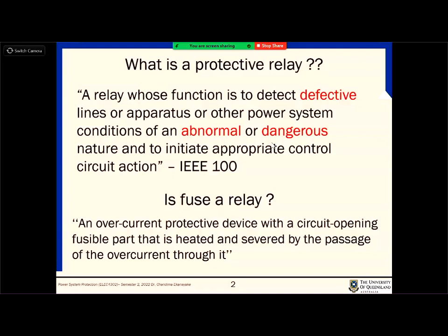So the full feeder is not disconnected now. A section of the feeder will be disconnected because you install it in parts of the network line. Like, for a feeder of let's say 100 kilometers, you can put it every 25 or 50 kilometers depending on the number of customers. So it's up to the design engineers where to put those things.